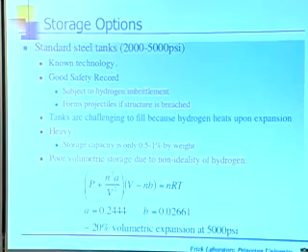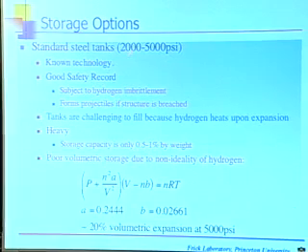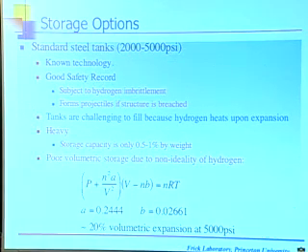So what are our options? Steel tanks. We have steel tanks, no problem today, that'll do 2,000 to 5,000 psi. A lab tank is usually somewhere around 2,000 to 2,500 psi. 5,000 is not a problem. They've been built. They've been around forever. OK, so known technology. Great safety record if you ignore a few minor mishaps that weren't hydrogen but other high-pressure gases.